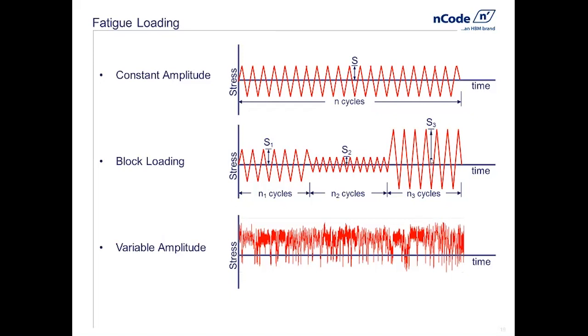Or an even bigger challenge is, what happens if we go measure load data? Or what if we introduce track roughness or wheel out of roundness or some kind of random vibration of some sort or something highly more variable? Anytime you measure strain or loads data, we end up with what I would refer to as a squiggly line, or technically we'd call this a variable amplitude load history, with all these different, almost random looking cyclic content. So what cycles are in here, and how does this lead to potential for product failure?